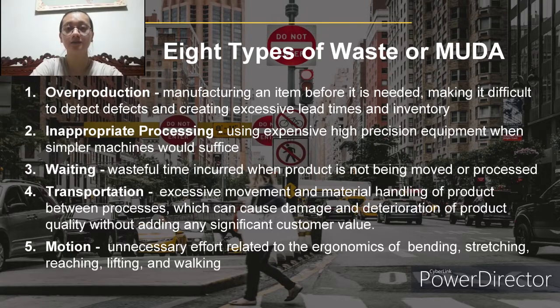Waiting: wasteful time incurred when a product is not being moved or processed. Transportation: excessive movements and material handling of product between processes, which can cause damage and deterioration of product quality without adding any significant customer value. Motion: unnecessary effort related to ergonomics and bending, stretching, reaching, lifting, and walking.